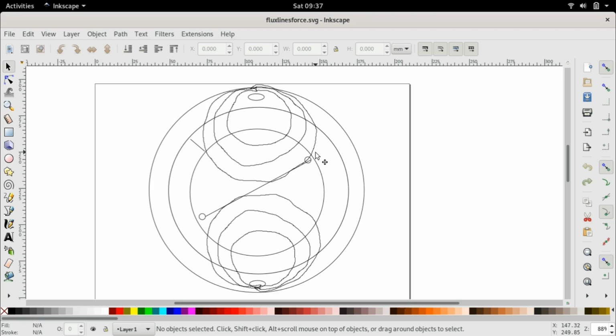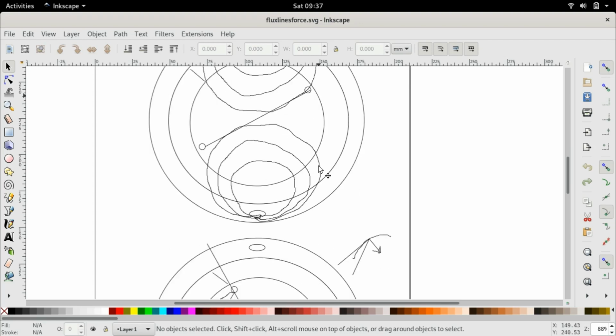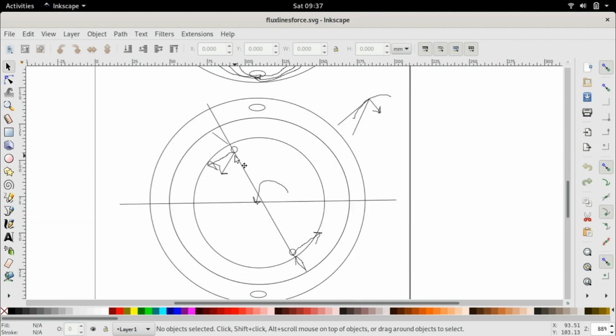So now this current, which flows through the rotor, is once again in an external magnetic field. Now you might argue that this current is actually produced by this magnetic field. So they know each other. They are all associated. But that doesn't matter. From the simple laws of physics, if there is a current carrying conductor in an external magnetic field, a mechanical force will be produced on this conductor. And the direction of the mechanical force can be determined by Fleming's left-hand rule.